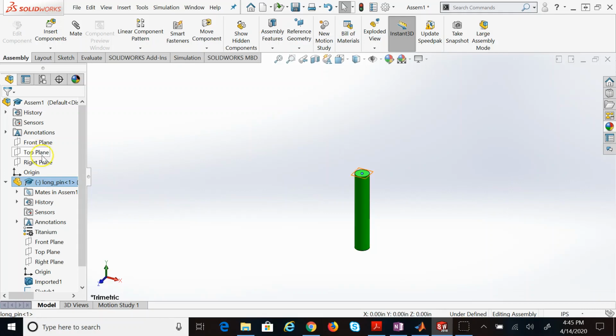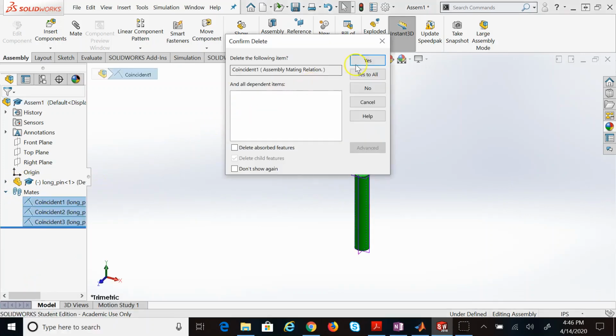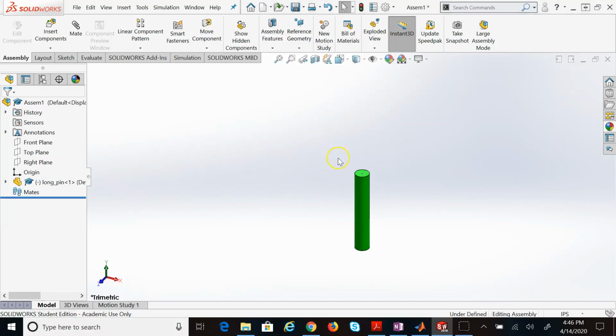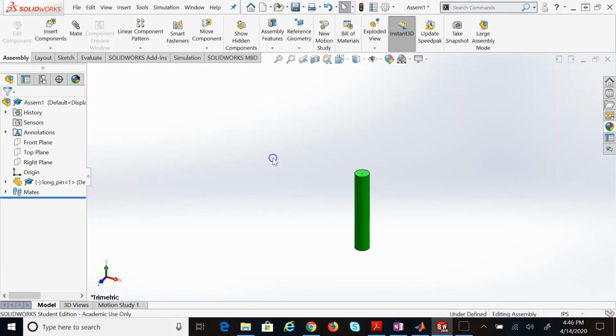And it is under intersection 2, which is origin. Or there is actually origin. You could make life much easier for yourself by all you do is, instead of all these 3 coincidences, what would you do? You just go ahead and choose this guy, and then hold down and select origin, right? And then you make them coincident. That's much easier, right, than 3 coincidences. But if you don't see this, which you should always see, that's another alternative.